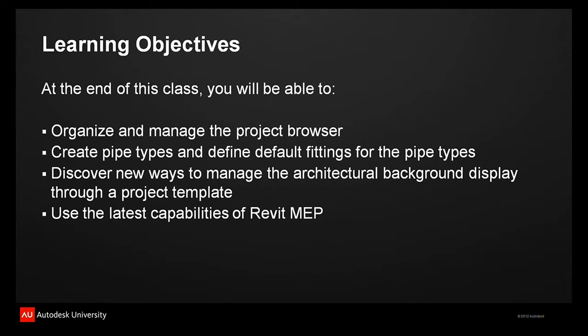Very good. I'm going to give it to him because I believe that is the correct answer. All of the others, you can activate work sharing starting from a project or from a template. What you cannot do starting from a template is control the visibility of linked files, and you cannot define default view templates to those. The Revit links dialog box in visibility graphics does not appear until you have a linked file in your template. So that, to me, was the correct answer.